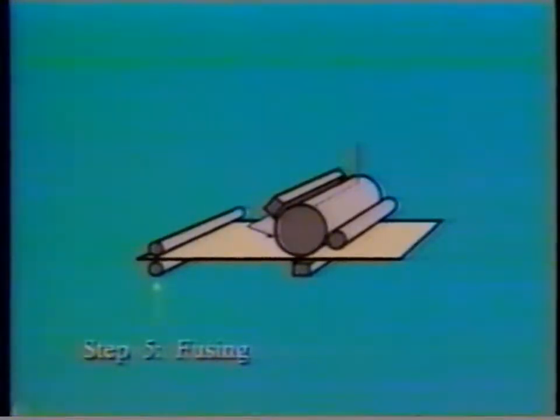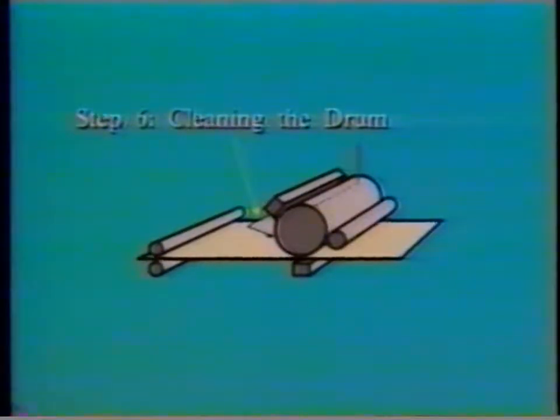Step 5, fusing. The paper with its loose, unbonded toner image is now passed through rollers which use heat and pressure to fuse the toner into the paper to make a permanent image. Step 6, cleaning the drum. The transfer of toner is never achieved completely. The drum must be cleaned before the next copy can be made. A soft plastic cleaning blade removes loose toner from the drum. The drum is now ready for the next page to be printed.